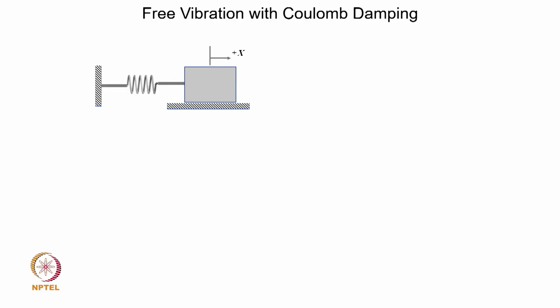also called Coulomb damping. It so happens that whenever the body has a relative motion, at the interface there is dry friction, which is going to generate a dissipating force, which is the frictional force, and that frictional force is the damping force that we have. Because it generates heat, the energy available for the vibratory system gets dissipated, gets converted into heat, part of it.